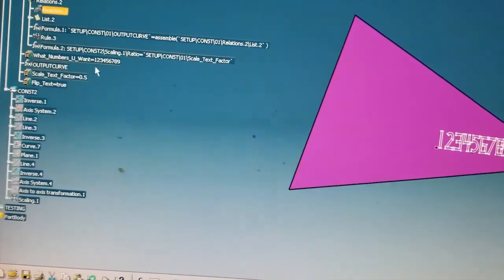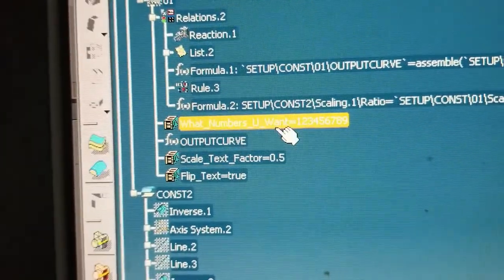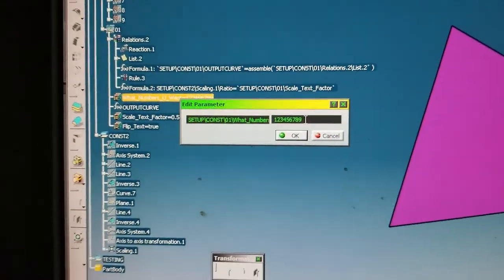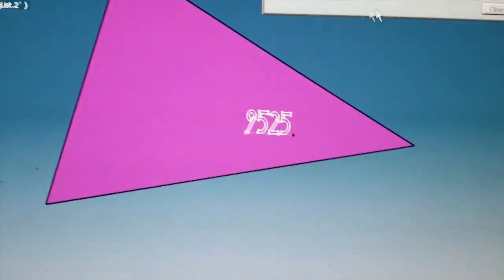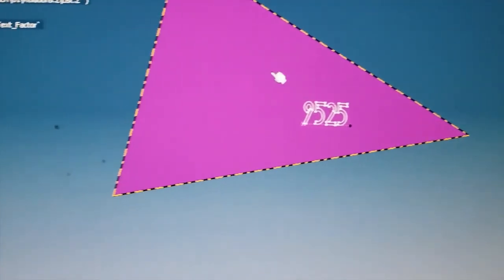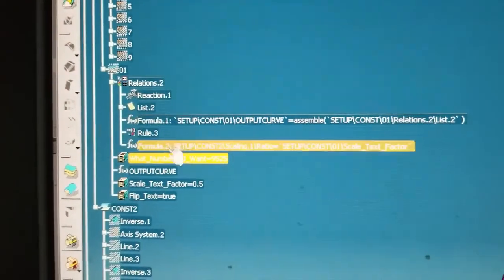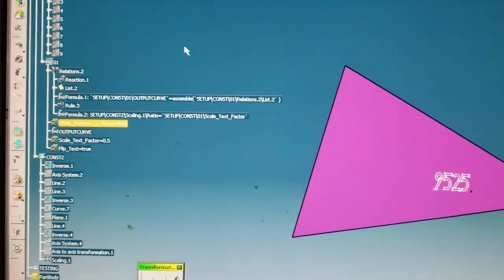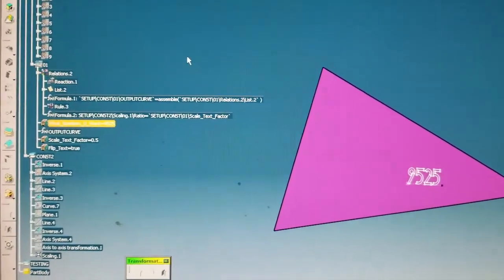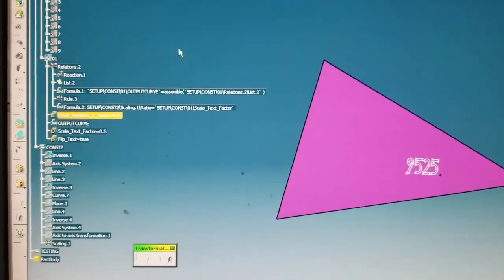There's some rules for the orientation of the text and everything, but now all you can do is take a simple parameter like this. Right now it just does numbers, but you can put in any number you want, and it will put that number on the thing, and then this is extrudable. You can make it into solid. It's lightweight, only something like 7 objects, and I just made sketches for each of the characters, because every time I tried to use an actual font, there were so many curves and lines and constraints that it made the whole item so heavy.